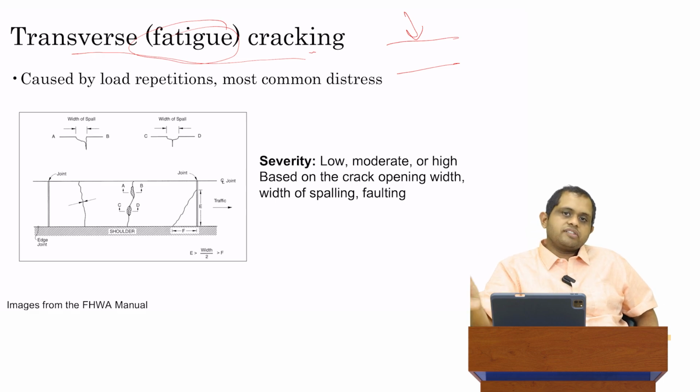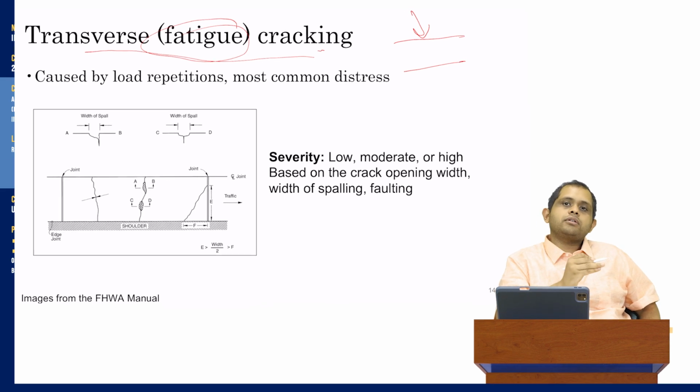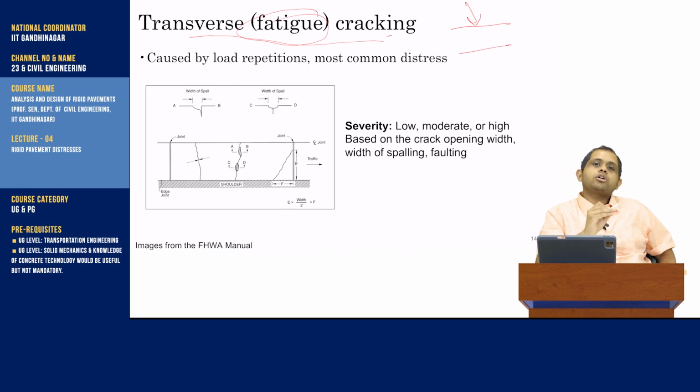And pavements, as we shall see in some lectures later, and rigid pavements in particular, are designed based on fatigue theory. And within fatigue theory, we generally want to see, for a given amount of traffic, what is the length or the number of transverse cracks which are developed. So that's called transverse fatigue cracking.